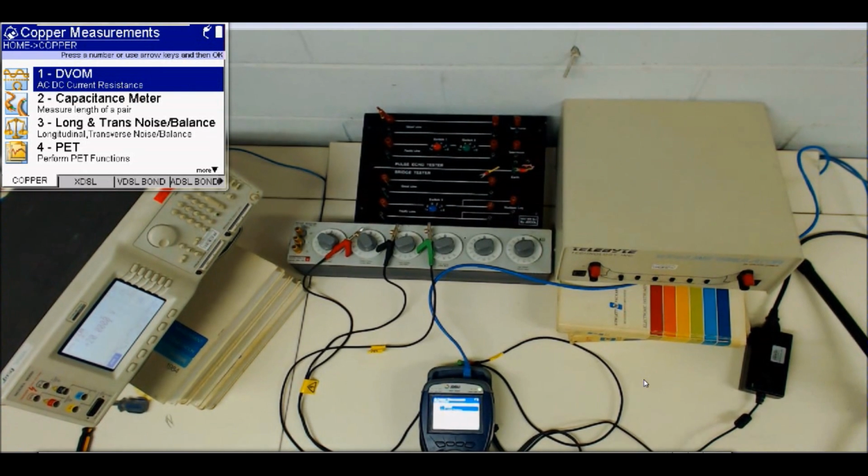In this section we said that we are going to measure an open circuit in regards to two different measurements. That is, we can find the length of an open circuit on a good line in two different ways. The first way would be measuring the capacitive length of the line. How are we going to do that? Fairly simply. If we go in the copper measurement menu, that is the initial screen of the unit,